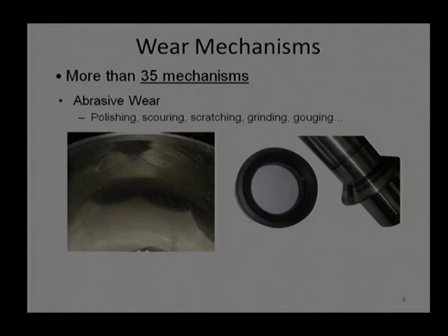Once this carbon graphite layer is getting deposited on the stainless steel surface, we are going to reduce the coefficient of friction and subsequent wear. In other words, initially there will be high wear because of the transfer of the layer from carbon graphite to stainless steel, and subsequent to that the wear rate will come down and friction will be reduced. We may say the coefficient of friction is initially around 0.3, 0.4, and subsequent to transfer of this layer, the coefficient of friction may be reduced to 0.2. So, almost 50% benefit is there, and we desire it.